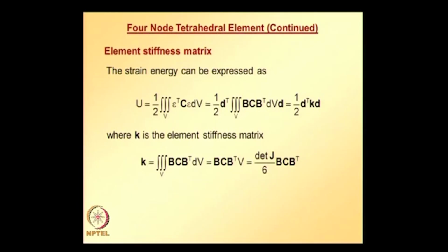If you recall, when we were deriving finite element equations for the 3 node triangular element, the determinant of J is twice the area of triangle.